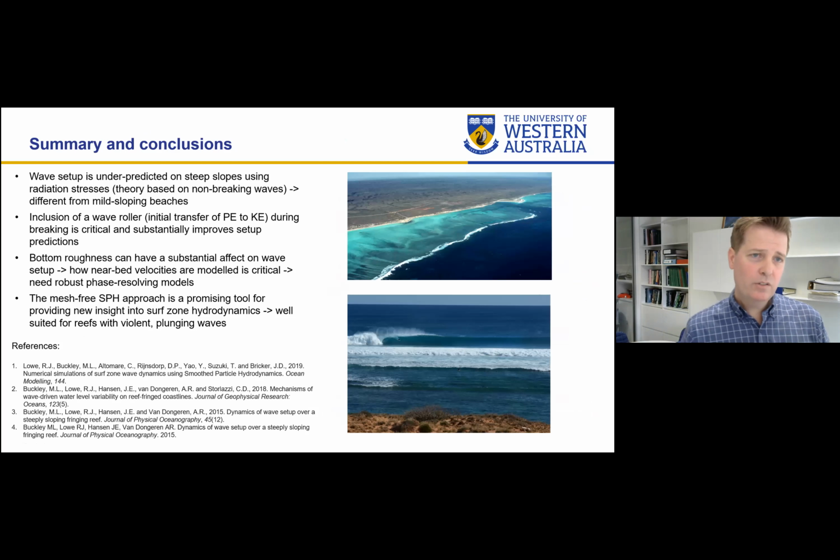So just to conclude, one of the things we've done is really shown how we can improve predictions of wave setup and understand why it's underpredicted on steep slopes using just simple radiation stress theory based on linear wave theory, and the differences between what occurs on mild sloping beaches.